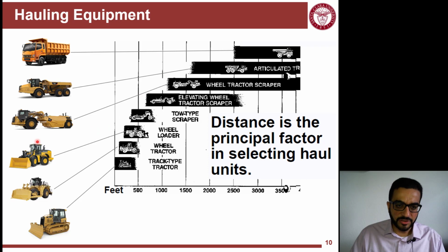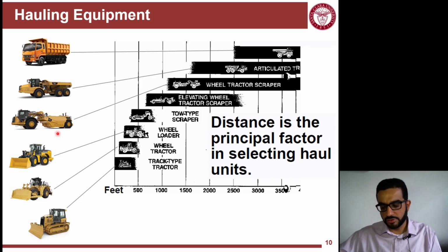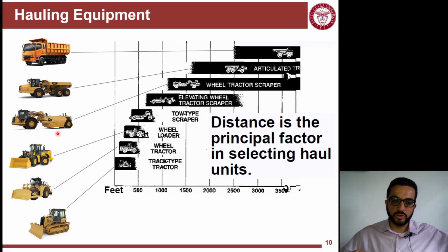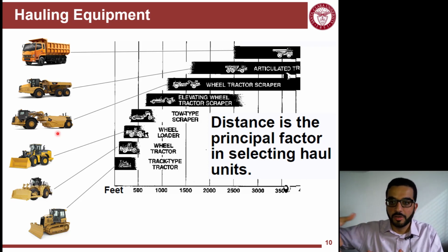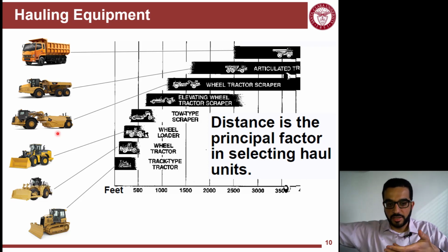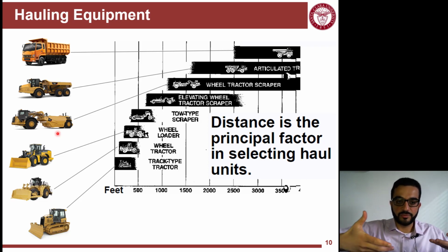Scrapers are very interesting equipment. They have this belly here, where they go into what we call the cut area, where you are cutting or digging the soil, and they move it to the fill area. So these operations, they call it cut to fill. You go to the cut area, and the scraper lowers the belly and scoops the soil. It's exactly like scooping ice cream, kind of. The soil gets into the belly, and once it's full, the belly lifts up. So now you're moving as if you are a truck.